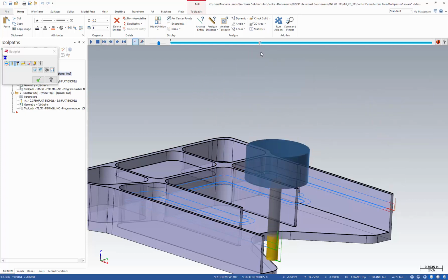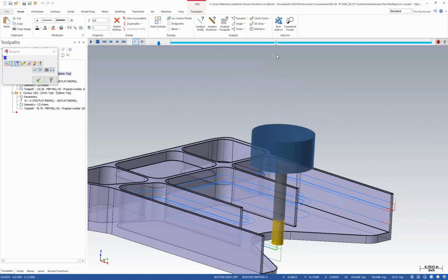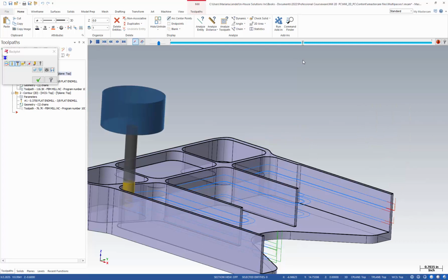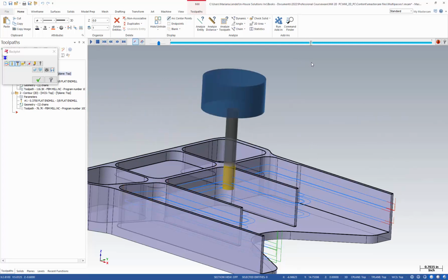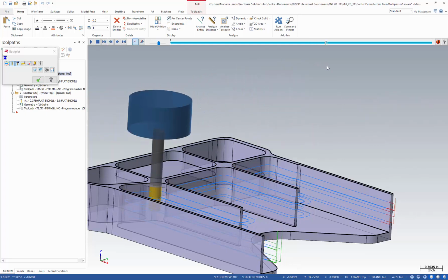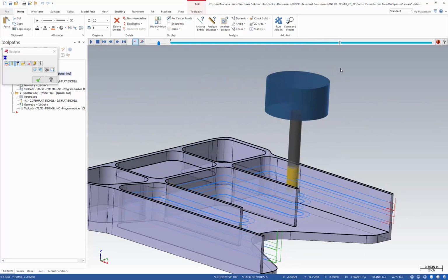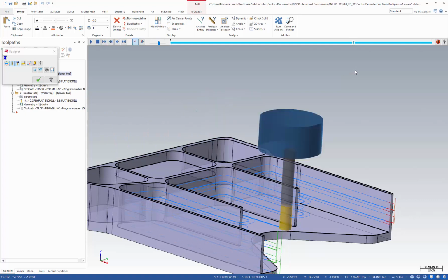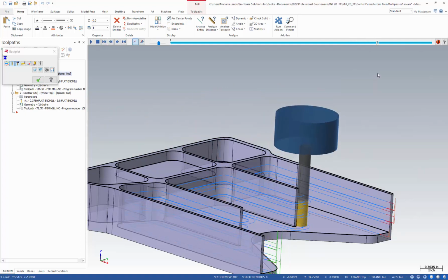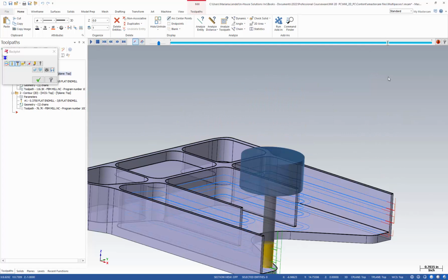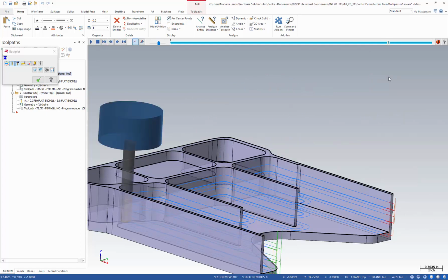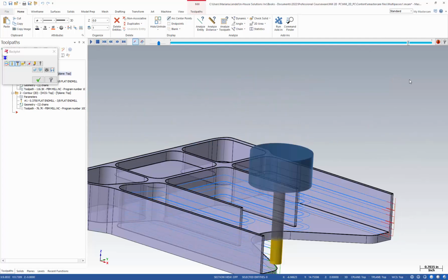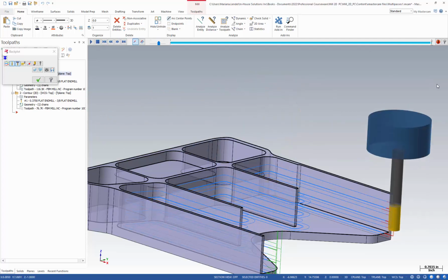Takes another Z depth and will perform the 2 roughing passes, and then will retract and creates the finish pass in between the depth of cuts and makes the finish pass at the same Z level as the second depth of cut. And the last depth cut, doing the 2 roughing passes, retracting the tool in between the last depth of cut and this one, and creates an extra finish pass and finish the part at the bottom too.